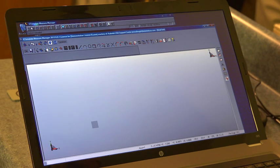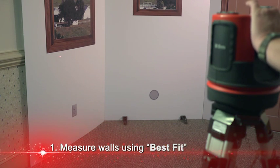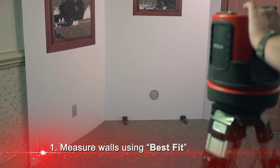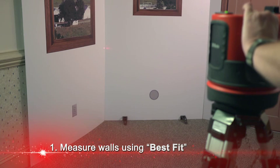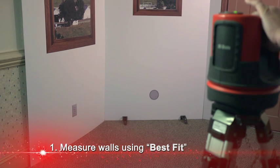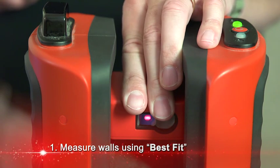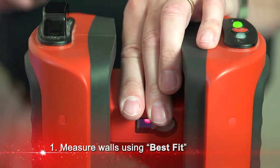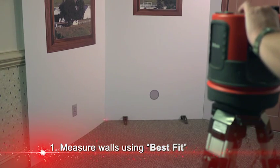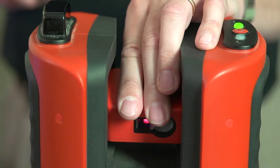I'm going to go into my line function in the measuring tool, and our system has the capability of doing what we call best fit. This means I can take more than 2 points for a line and it will actually do a best angle through all of that data. Obviously, lots of walls are not plumb or straight, and I want to be able to get the best angle possible. So as I'm taking data, you'll be able to see that these points are not plumb on the screen.